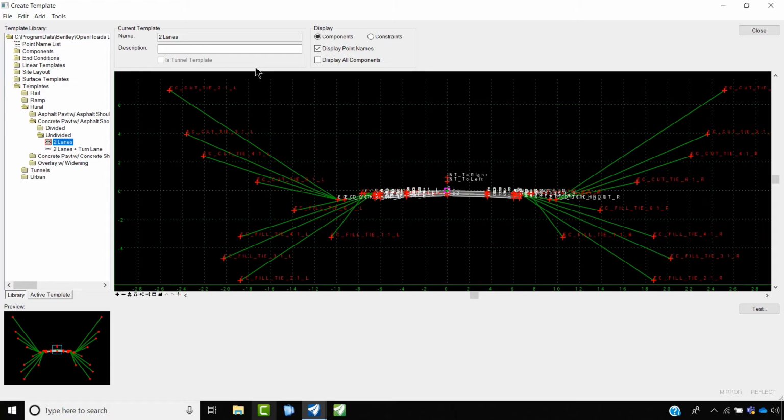This will take me into a separate template window, where this template file, at the end, is a .itl file, the civil templates metric .itl file. This has been taken from the workspace of the terrain training and templates, where all your cross section data being created is stored in the .itl file format.